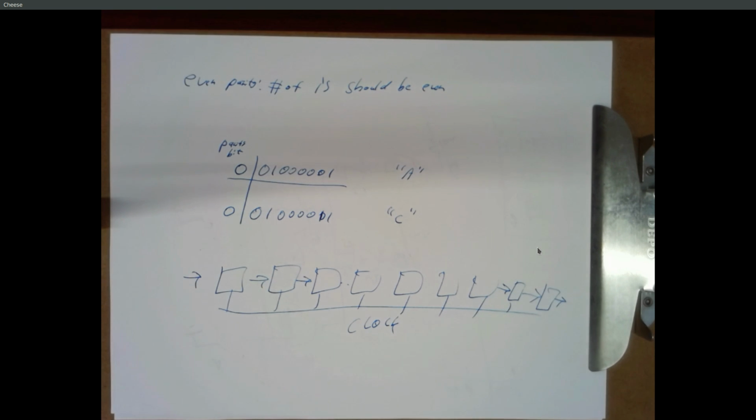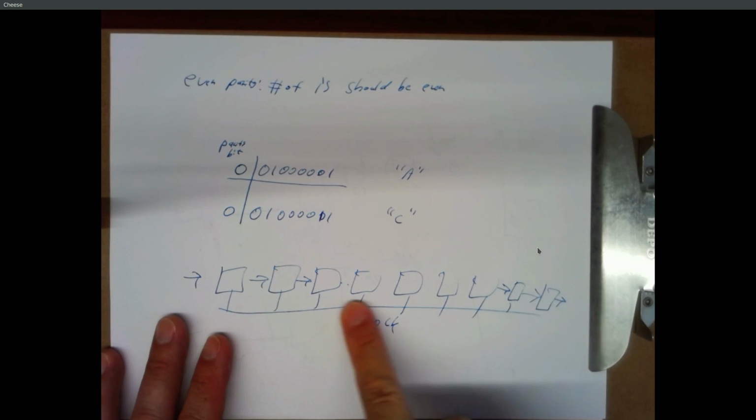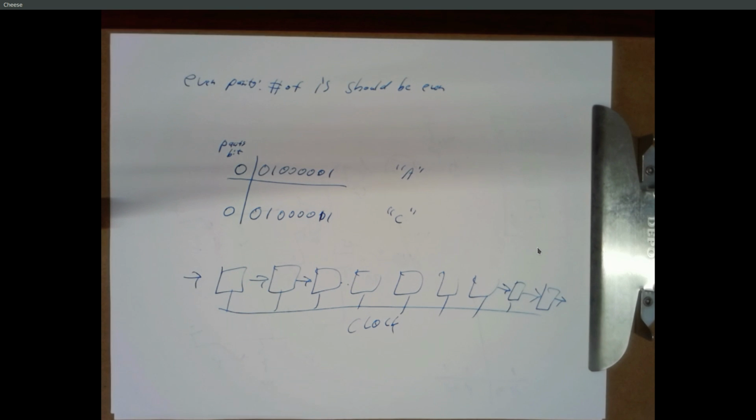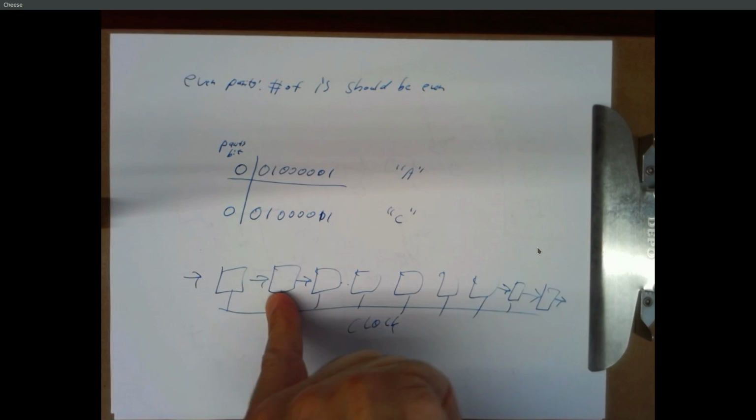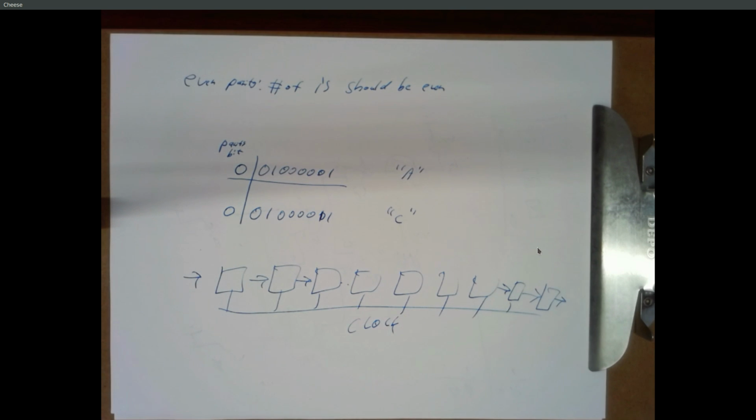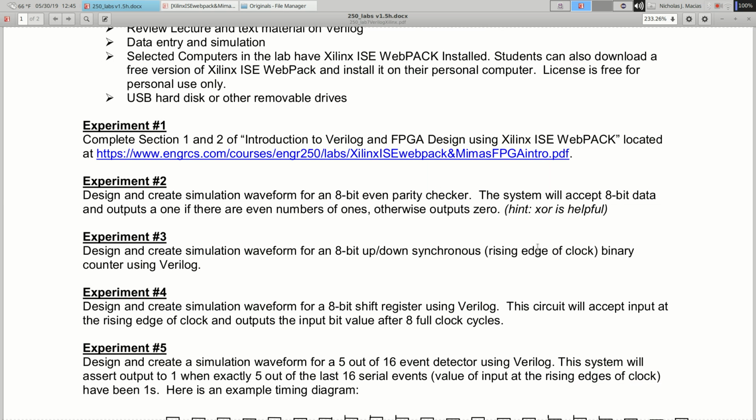This is really great if you like playing music. You can make a nice delay system with this. Digitize your music, feed it in through a delay like this, and depending on how many clock ticks it takes to come out the other side, you get a version of your music delayed in time. You can mix that with your original and you got a nice echo effect. You can also take that and feed it back in, you can get a reverb.